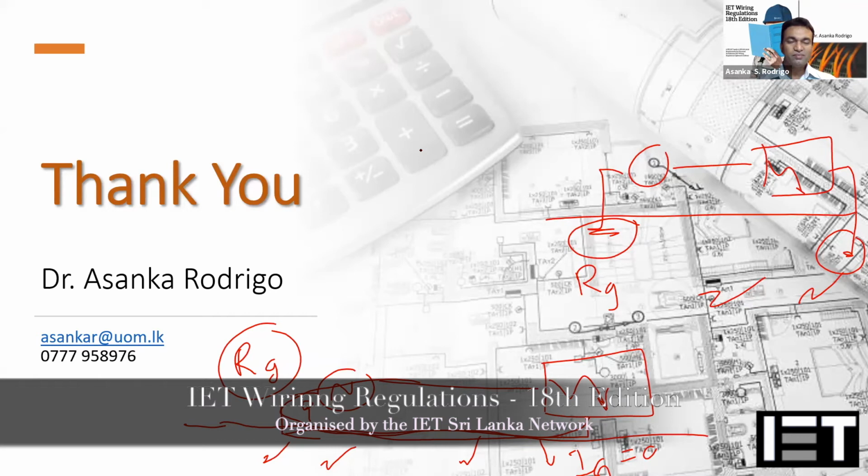Dr. Asanka, what type of sensitivity would you recommend for that meter cubicle RCCB? As I said, you have to decide your coordination. It's not only the RCD; sometimes you may need an earth fault relay with a delay as well. If your building is very complicated, with different levels of distribution boards, you use a normal general-type RCD at the end level. At the next level you may use a type S RCD. At the main distribution board you may use an EFR, and for the main cable you may also need an EFR with a certain time delay, because this coordination should be there. Otherwise, even for an end-level earth fault, there can sometimes be a trip-off from your meter part. So that coordination should be done.